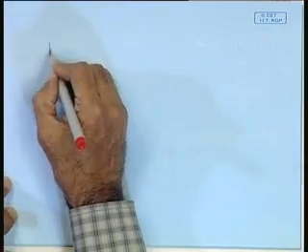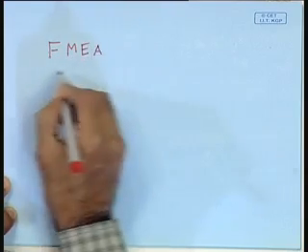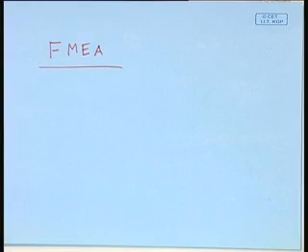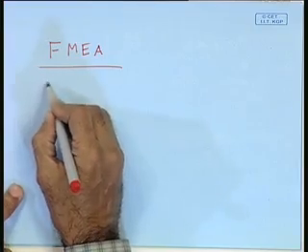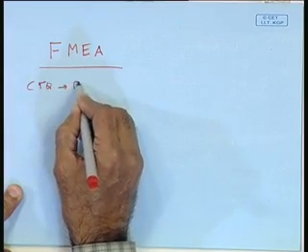If I've got anything, I've got a simple product here, I've got a pen in my hand. In what different ways could this pen stop working? That is the question I have to ask, and I have to construct this engineering worksheet, and that is called the FMEA, Failure Mode and Effects Analysis Worksheet. So that worksheet will be called an FMEA worksheet. And what this one really does is, it looks at two things. How might a CTQ fail? I have a CTQ that fails.